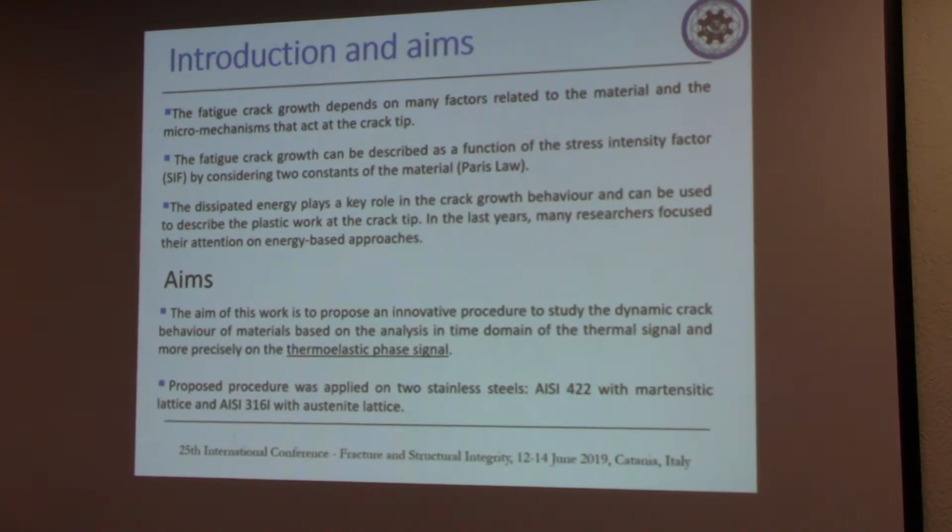Okay, we all know that the fatigue crack growth depends on many factors, such as the micro mechanisms that act at the crack tip. In particular, the crack growth can be represented as a function of the stress intensity factor in the Paris law. In the last years, many researchers focused their attention on energy-based approaches, because the dissipated energy at the crack tip plays a key role in the crack growth behavior.